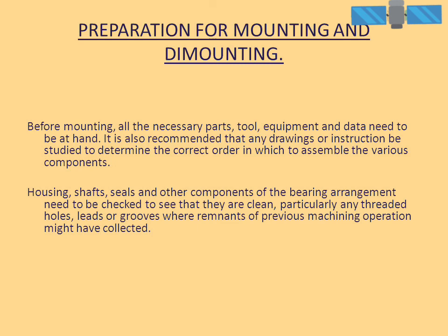Before mounting, all the necessary parts, tools, equipment and data need to be at hand. It is also recommended that any drawings or instructions be studied to determine the correct order in which to assemble the various components. Housings, shafts, seals and other components of the bearing arrangement need to be checked to see that they are clean, particularly any threaded holes, leads or grooves where remnants of previous machining operations might have collected.